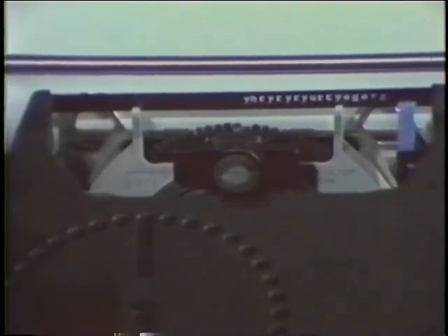Now watch as we explain the sequence of movements of the print wheel. The print wheel makes 3 revolutions. The first rotation of the print wheel is to make sure the selection motor hub engages the print wheel. The second rotation homes the print wheel. Once the homing hole is detected, the print wheel is rotated back to the home position. The final rotation is to sense the pitch and impression holes.